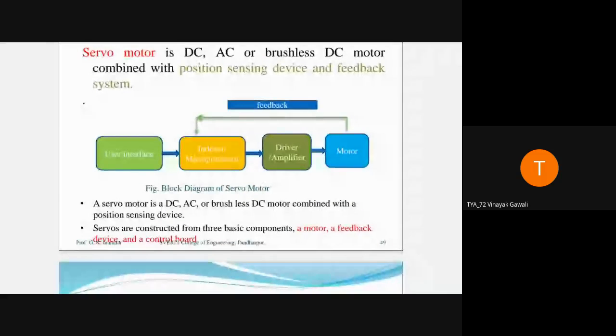The tool will come back after completion of work. That is, in drilling, after completion of drilling the tool should be at its original position. While coming back, is there any need for 1000 RPM speed, without wasting energy? At that time the controller and sensors will reduce the speed or switch off the spindle directly. This provision is also available in the servo motor.